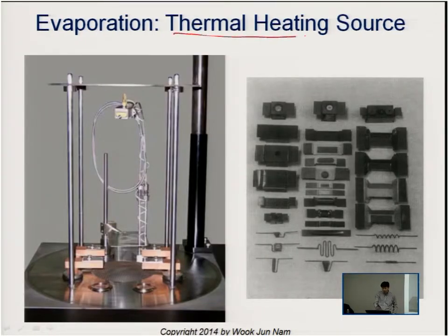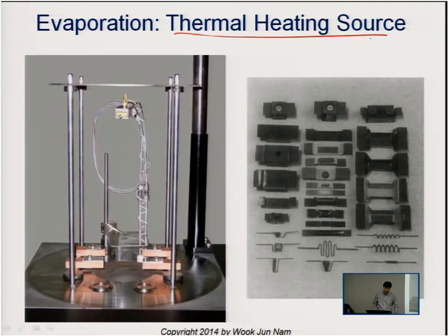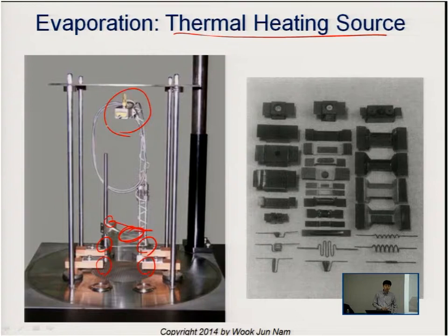So this is the typical configuration of the thermal evaporator. There are two electrical posts, and sometimes there are shutters installed right on the source, and this is the quartz thickness monitor. We're going to talk about this in a later slide.